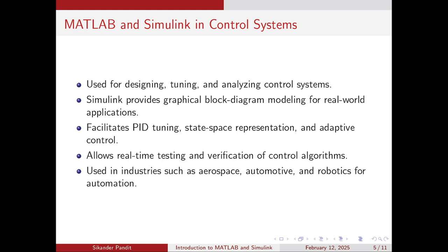Used for designing, tuning, and analyzing control systems. Control systems are basically autopilot designs. You can tune, like, a PID controller. What is Simulink? Simulink provides graphical block diagram modeling for real world applications. Suppose you take the example of an aircraft and its propeller, you can model it in a block diagram. Simulink provides that graphical representation of a particular subsystem and the complete system.